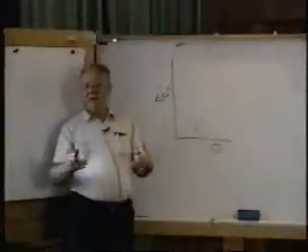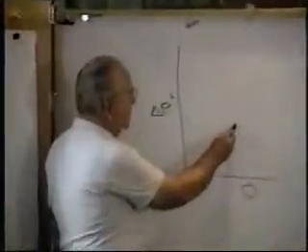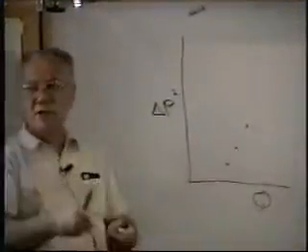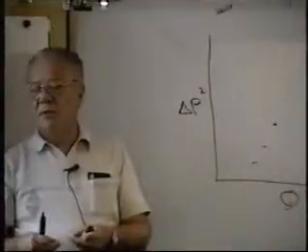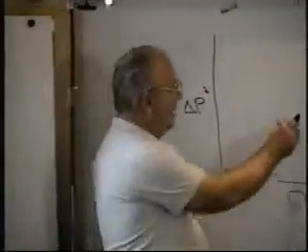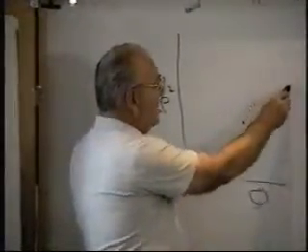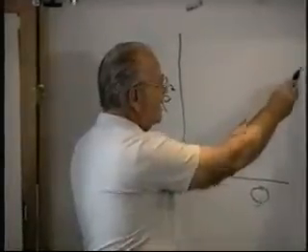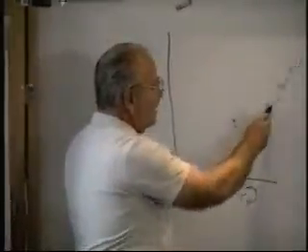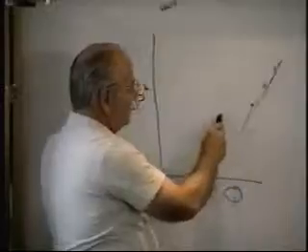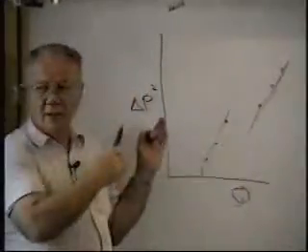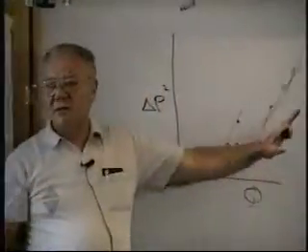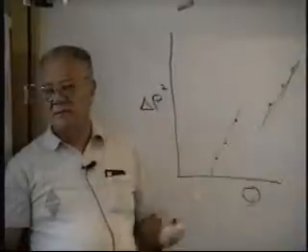And then when you finally get at a high enough flow rate to where the bottom hole flowing pressure is lower than the shut-in pressure of the other layer, and the data exists because I analyzed the data for E and P, there was a shift in the deliverability curve to the right once the other layer started actually contributing.